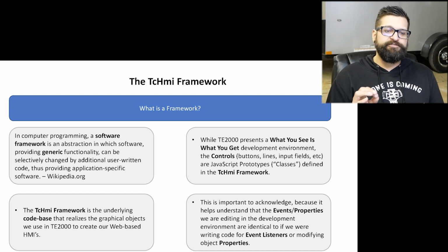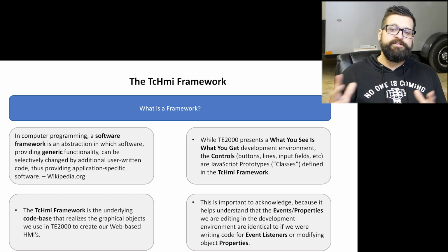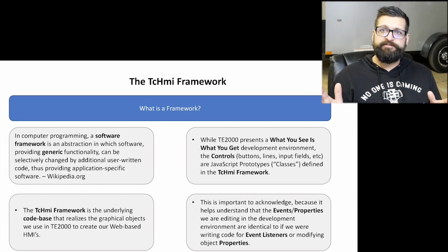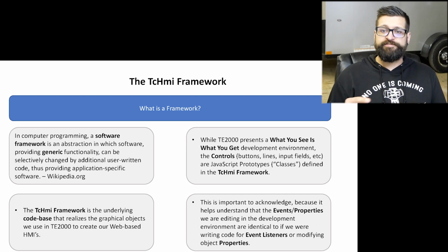So the TcHmi Framework is the underlying code base that realizes the graphical objects that we see in the TE2000 web-based HMIs. While the engineering environment presents you with a what-you-see-is-what-you-get, or WYSIWYG, development environment where we're dragging and dropping these controls over, underlying those controls are JavaScript prototypes, also called classes, but I guess technically they're prototypes.